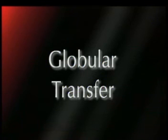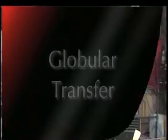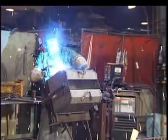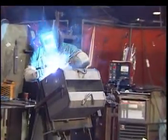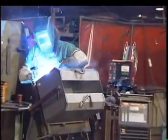Globular transfer uses higher energy levels than short arc and higher wire feed speeds. This process offers very fast follow or high speed characteristics, high deposition rates, and very good penetration. However, when viewed up close, globular transfer exhibits extreme violence in the arc.